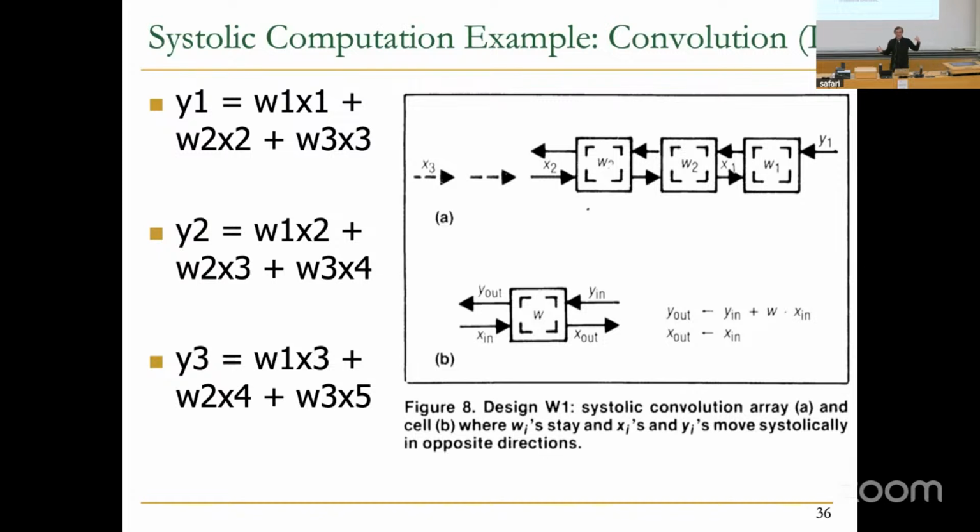This is beautiful. Inputs are coming in one direction. While the inputs are coming, processing elements are doing the operation, and outputs are going in the other direction. There's no instruction here. We got rid of all the instructions. Forget about all of the MIPS, x86, there's none of them. This is a very specialized processor for doing convolutions. Is this beautiful? Yeah, so you can see now, the instructions are gone, all of the overhead is gone. You can focus all of your effort on doing convolutions. Right? And that's the power of specialized hardware, as you can see, right?